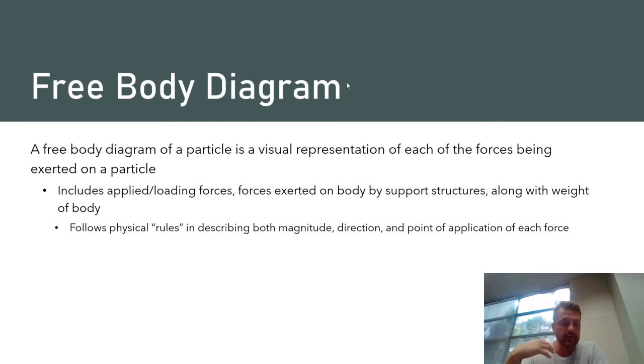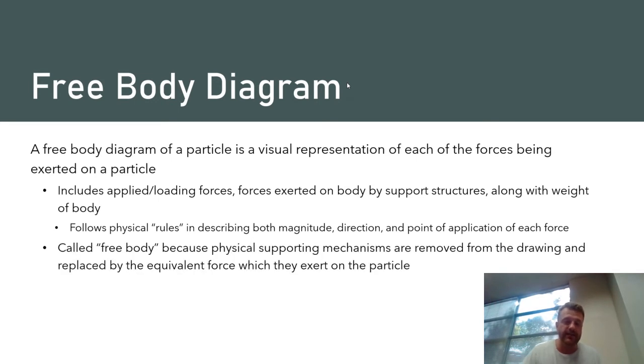However, we do want to accurately reflect on our diagram the magnitude and direction information whenever we're given it, because it will show us what quantities we're actually trying to solve for when we analyze our free body diagram, and whether we actually have a situation that's known as statically determinate, where we have enough equations that we can write in order to solve for the various quantities of interest that we need to determine.